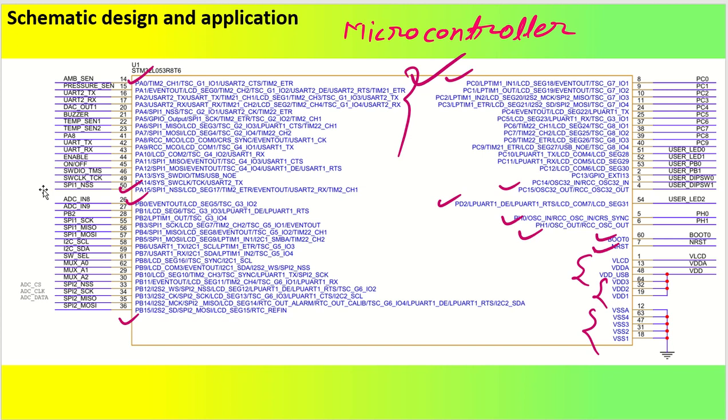I have tried putting in all the net names that we are going to utilize. If you want to make the symbol a little easier for your convenience, you can remove all the other functionalities and only keep your port names. If you only keep port names, that is more than enough. Since this particular device already has internal oscillators, we will not be using an external oscillator or external crystal for clock generation. We will use the internal oscillator for this application.